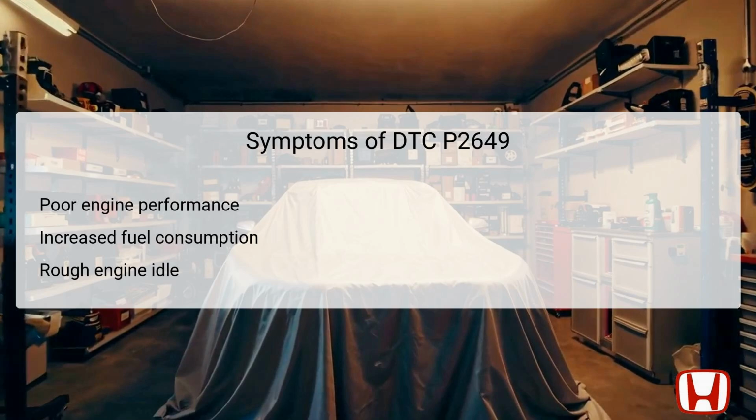Primarily, poor engine performance is a common outcome, as the malfunctioning solenoid affects the VVT system's efficiency. As a result, drivers might experience a decrease in acceleration response and overall power. Additionally, increased fuel consumption may occur as the engine struggles to operate efficiently without proper oil flow to the rocker arms. A rough engine idle can also be noted, as erratic valve timing leads to instability in engine operation. Recognizing these symptoms early can prevent further complications and repairs down the road.